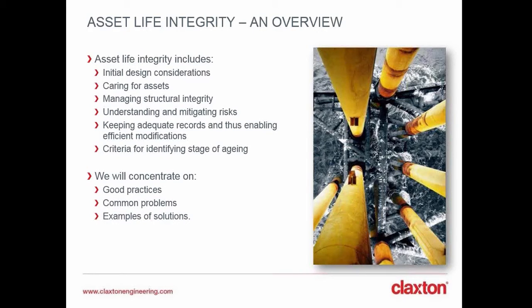When we mention here on the slide caring for the assets, this includes inspections and maintenance to keep them in working order. Managing structural integrity requires a well-developed maintenance program that considers active components, which are typically easily detectable, as any issue would mean they stop working. However, you'll also have passive components that appear to be functioning normally until the moment of failure, like the appearance of a leakage, for example, from a corroded pipe. So it's not until actual failure has happened that you realize there's a problem.